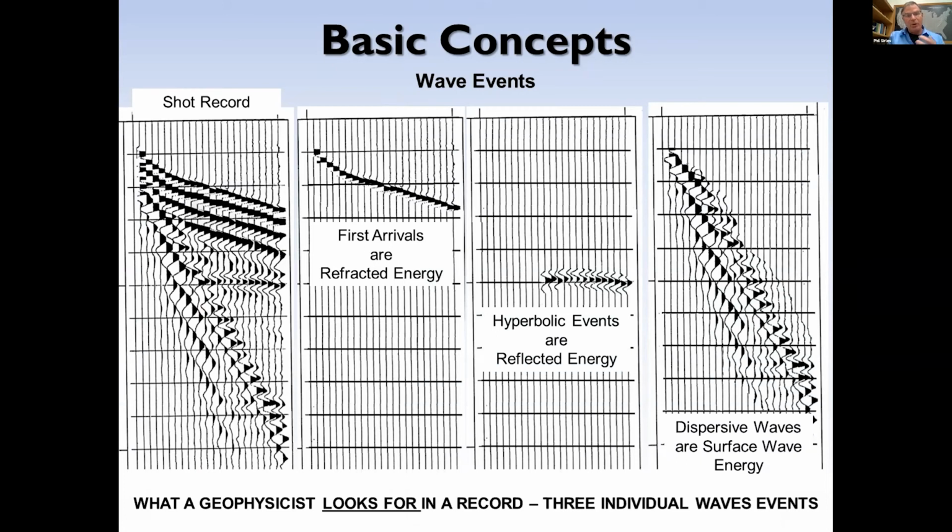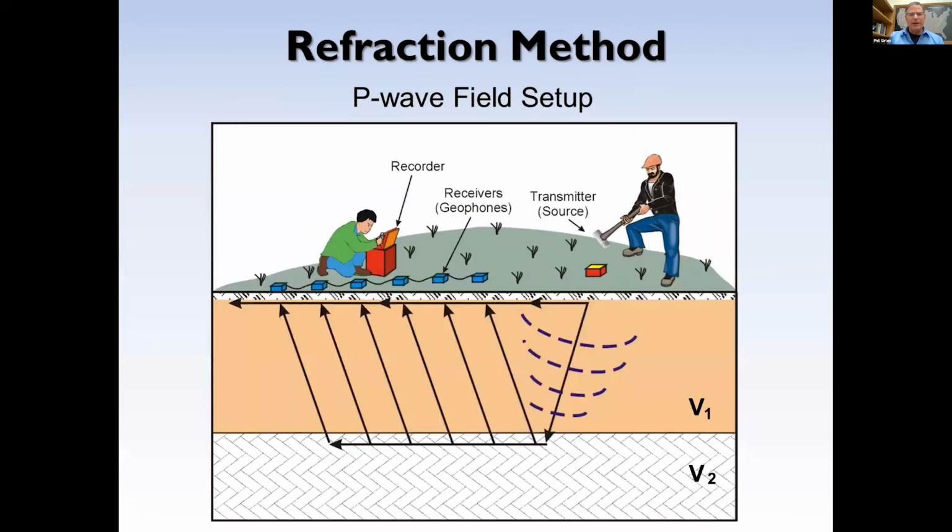And in the field, I'm looking for one particular type of that waveform. If I'm doing a reflection job or I'm doing a refraction, first arrivals, I've got to make sure I'm seeing those, that the site's not too noisy. So all of those are in the field records. You just have to know what you're looking for when you start collecting the data.